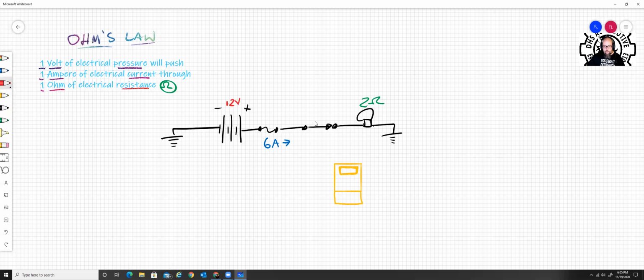So now on our meter we have different ports. One port we'll be using anyway is for volts and ohms. Another port that we're going to be using, usually right nearby it, is for ground. And you have leads that come out of here. When you hear the term leads, it usually refers to some kind of probe or wire. Now what's going to happen here is, you see this meter here. I'm going to be writing values out here that will go on the meter where you would set it. Otherwise we'll be in my poor drawing hell for the rest of this. I don't want to do that to you.